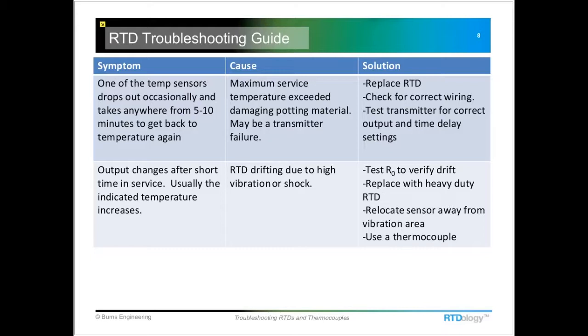The solution there was we beefed up the RTD to about an inch diameter, so that it would not shake or be affected as much by that steam injection.